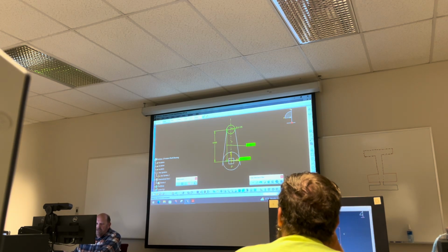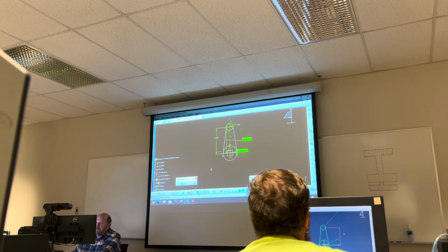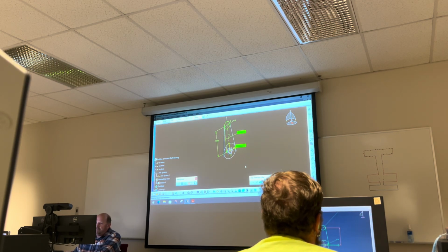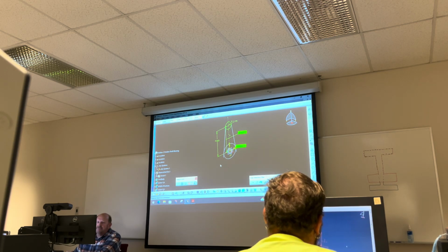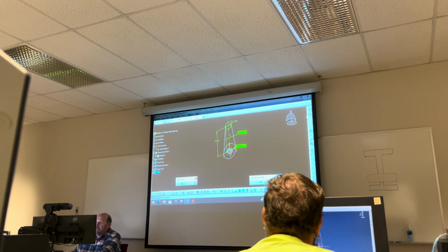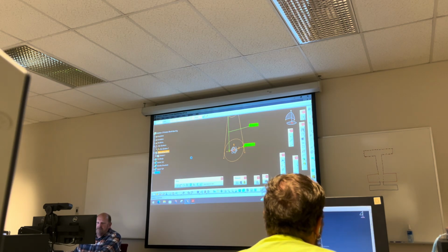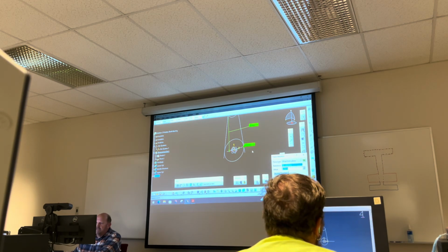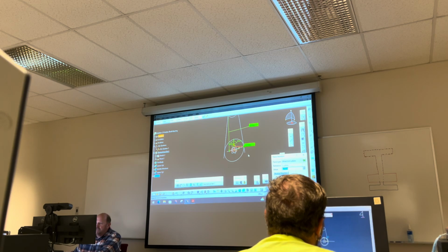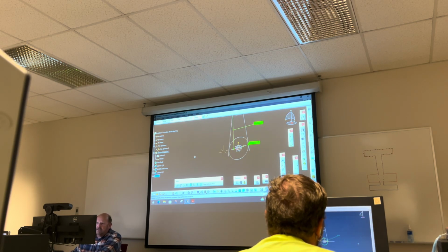So now that I've got the upper one defined and the lower one defined, I'm gonna go back to this middle piece. And so let me exit this sketch. Before I do that, I'm gonna go back into the geometrical set and say define a work object. I'm gonna offset a plane, the first one. And if you hit plane, offset from plane, I'm gonna pick this one. And this first one is gonna be 0.156. Okay, so there's my first plane.